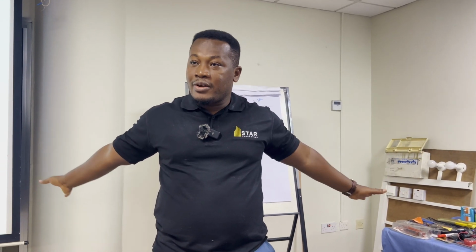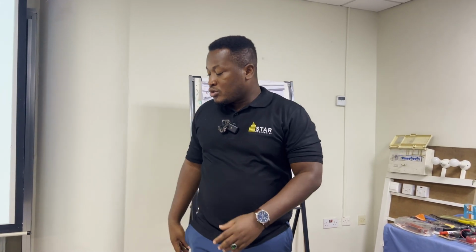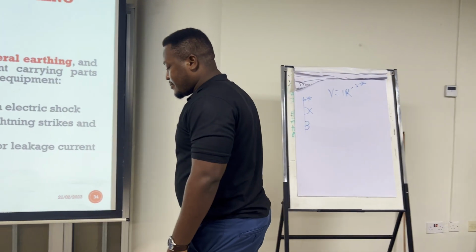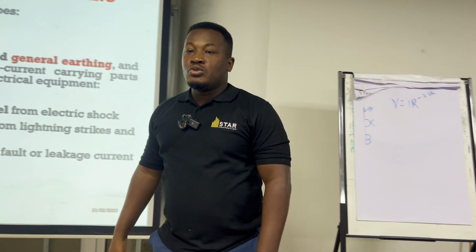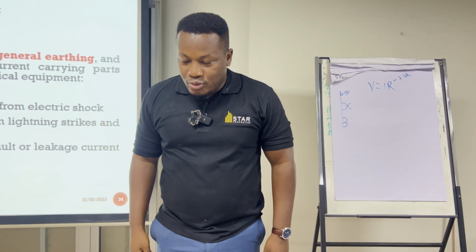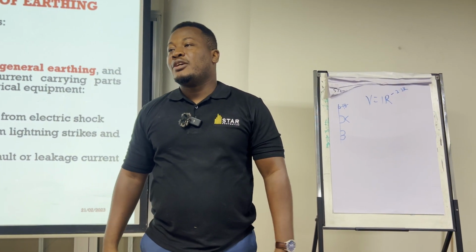If let's say there's a cable that has fallen down, high voltage, high tension cables, the 161s and, let's say, the 35 kV ones, you don't walk when there's a cable drop, because even though they've done the loop impedance test, we don't know which area is covered and which area is not. So we don't walk like this. What you do is hop. With your two legs together, you jump to the next stage and you jump.